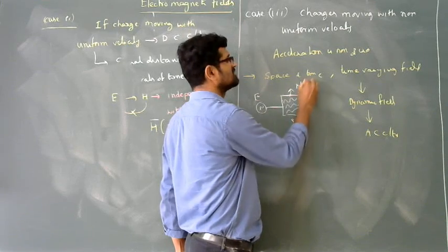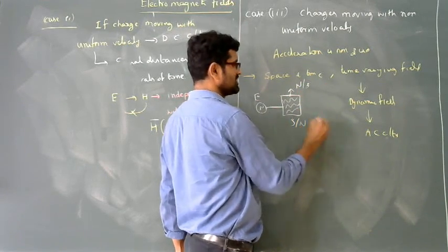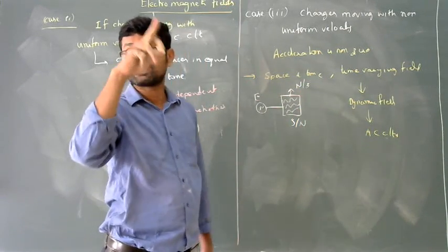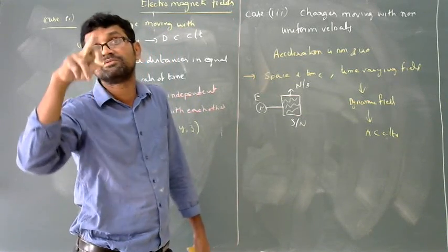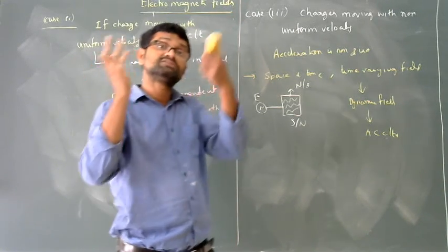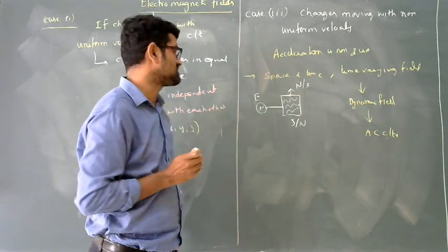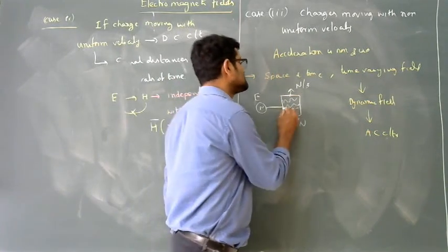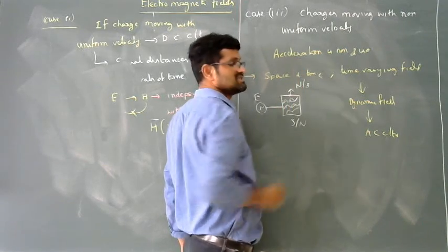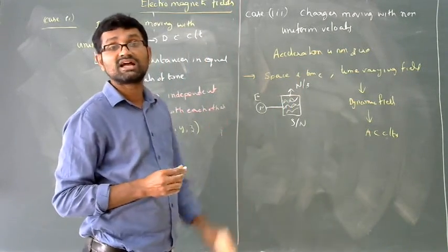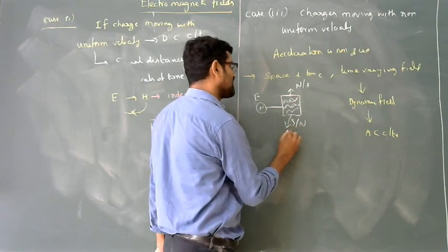One time it may be a north pole, another time it will be a south pole, depending on the variation of time. So for the positive half cycle, if a north pole and south pole form, then for the negative half cycle, the polarities get reversed. Current direction reverses means magnetic pole polarities also reverse. So the existing AC fluxes will cut the stationary conductor. Again there, electromagnetic fields will exist.